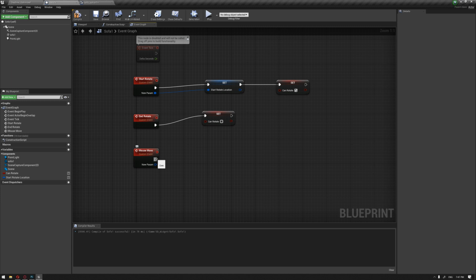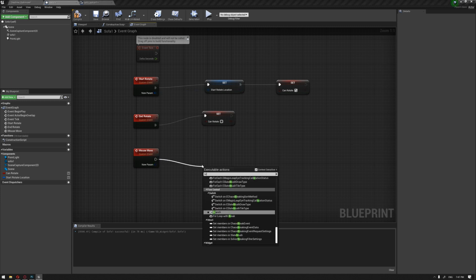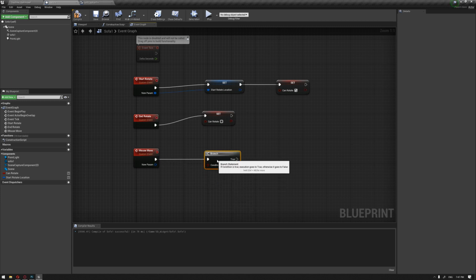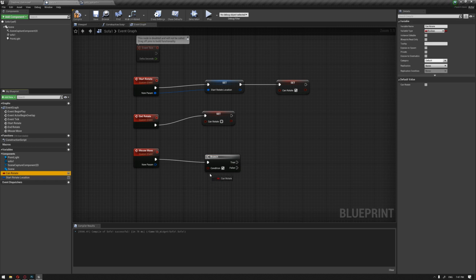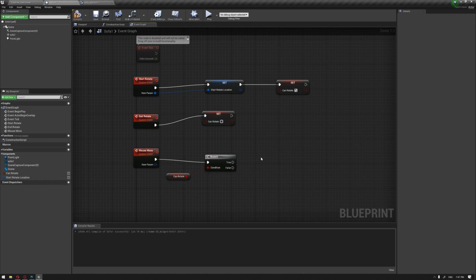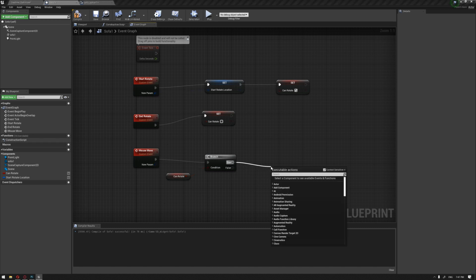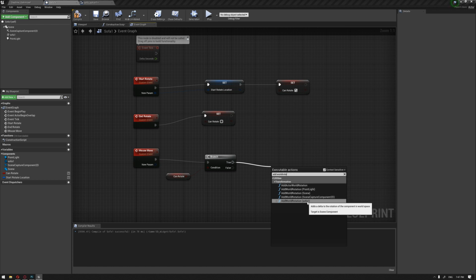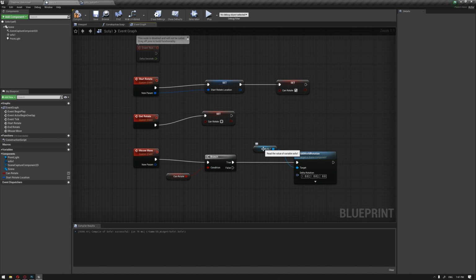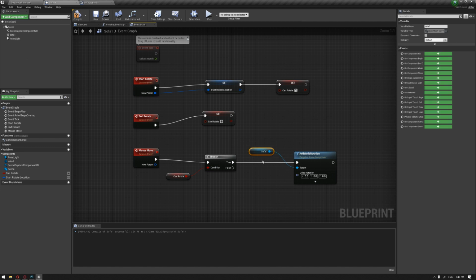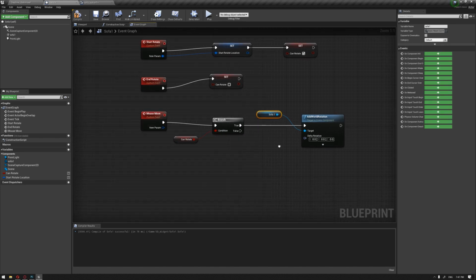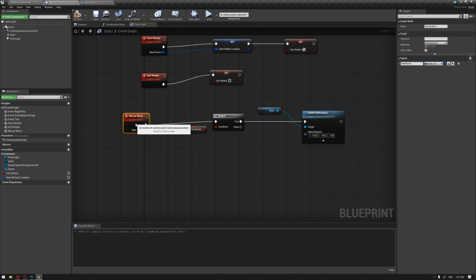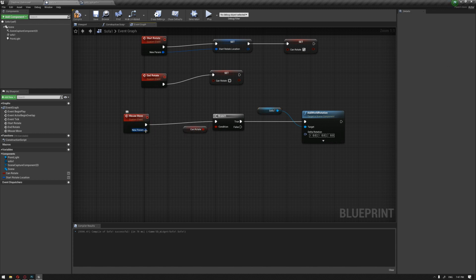And from this one, the mouse move, we're gonna get a branch, so we're gonna bring also the can rotate variable inside here. So if it is true, we're gonna need also to add world rotation. Okay, so it already brought the sofa static mesh reference, and this is something cool about the updates in Unreal Engine.